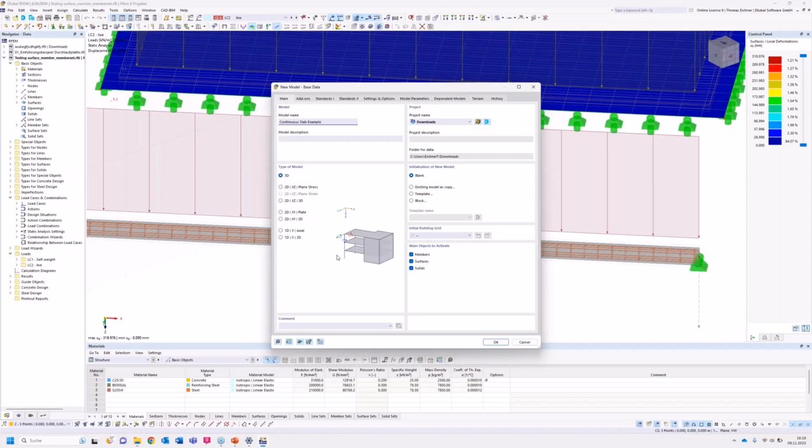Right in this 3D model, you see our 6 degrees of freedom. When we switch to our 2D plate model, we see it's simplified into just 3 degrees of freedom. Which means, for example, we don't have to define every support in the model. The program just supports the whole model in some directions, and that's what we're gonna use today, the 2D XY plate.